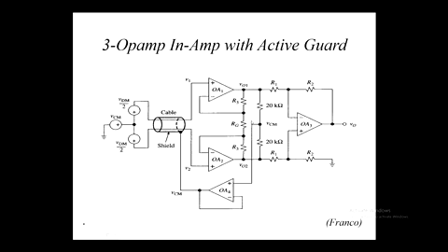But we think of these two as independent. We can think of these two op amps as being independent non-inverting amplifiers. And the gain would be set by, for the first one, R3 divided by RG on 2, right? Why RG on 2? Well, the midpoint here is virtual ground. So we have a gain of R3 on RG on 2 plus 1, and likewise for this one.